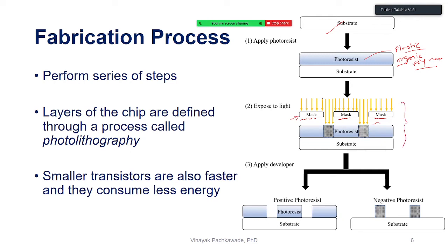this system to the light coming here. The light is coming and going straight down over here, but the mask is preventing the ultraviolet rays from reaching some portions right here and right here. So what is happening is that this particular area gets melted, or softened, so that I can later remove it. So what I'm doing is photolithography.